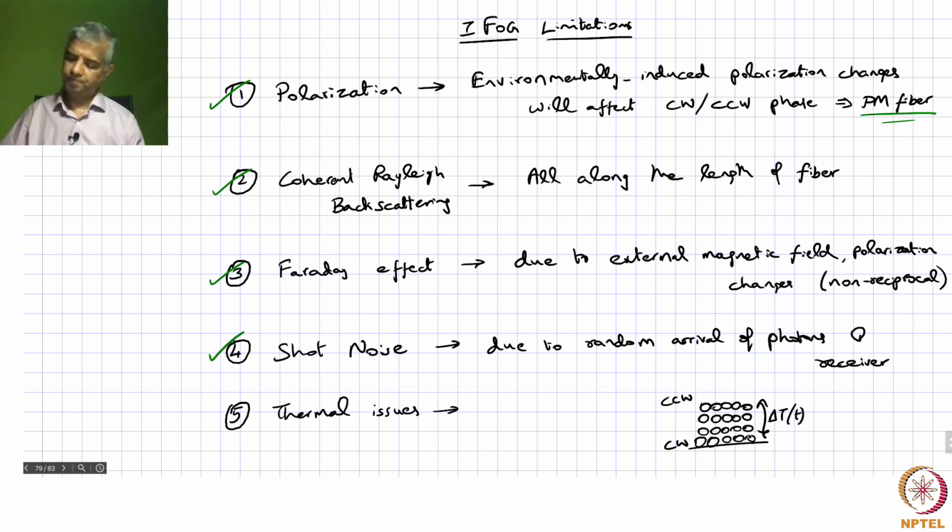Okay. So, what you actually want to do is something like this. You want to start with say the CW coil, and then wind from the other end. So, you wind one more layer corresponding to the CCW, and then one more layer corresponding to the CCW, followed by a layer at CW, and so on, right.